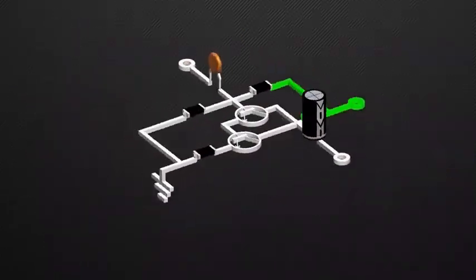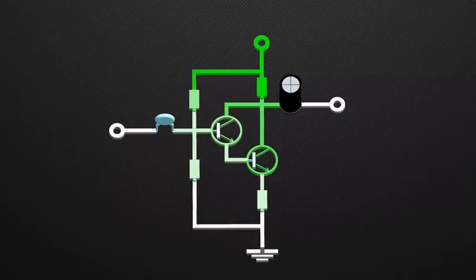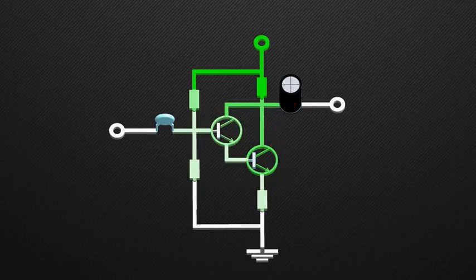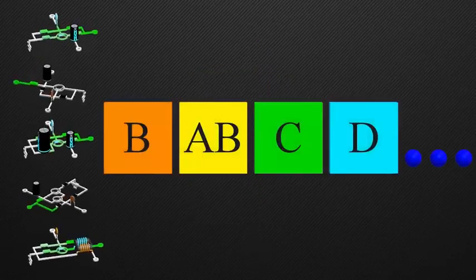This circuit uses the Darlington transistor in place of the single transistor. A Darlington transistor is two transistors within a single package, one small pilot transistor, and another larger switching transistor. This increases the current handling capacity and gain of the circuit. Also, this provides high impedance at the input and low impedance at the output.